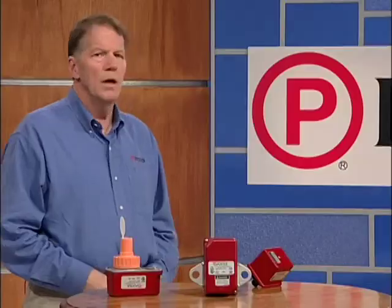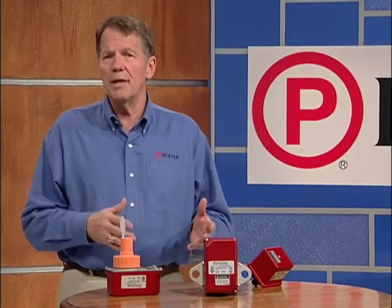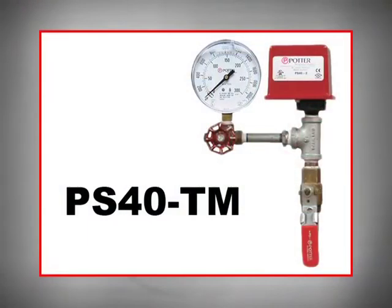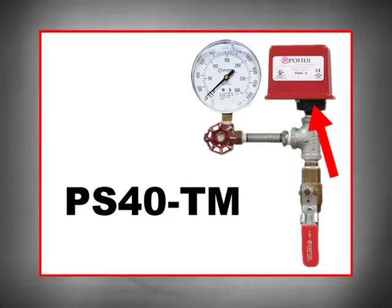The Potter BVL is a quarter-turn bleeder valve that facilitates initial setting and ongoing testing of the Potter PS series pressure switch. This valve is a time saver and eliminates the need to shut off the water supply and air compressor, open a union, and bleed off air from the entire system. By using the BVL, only the air between the BVL and the pressure switch is bled.